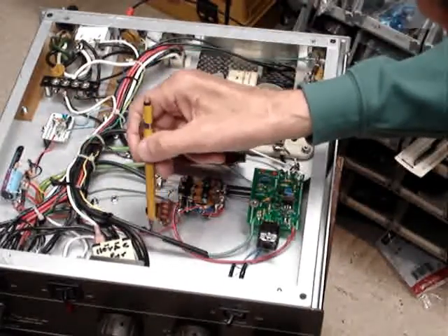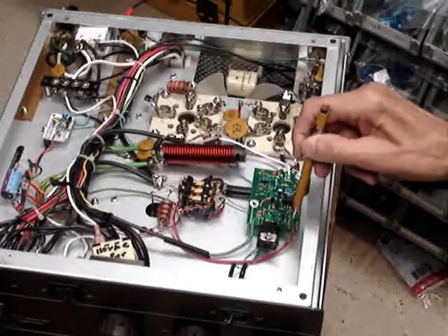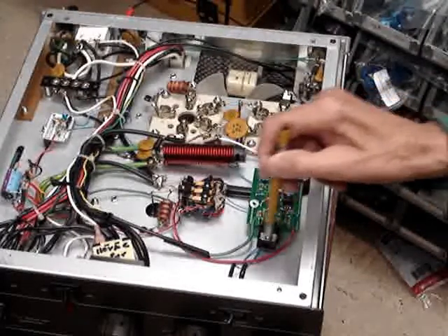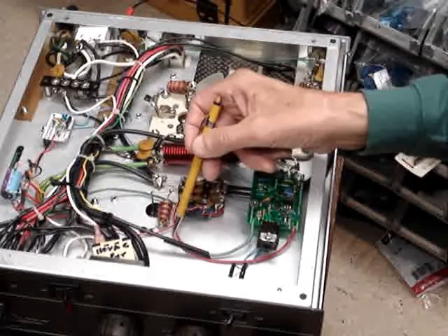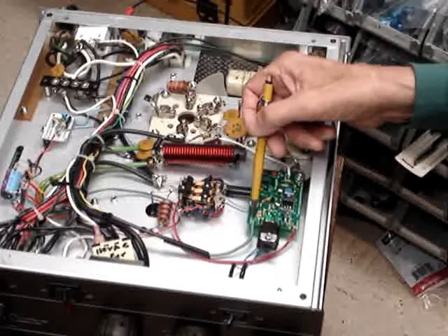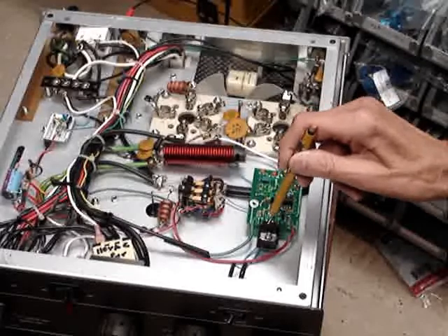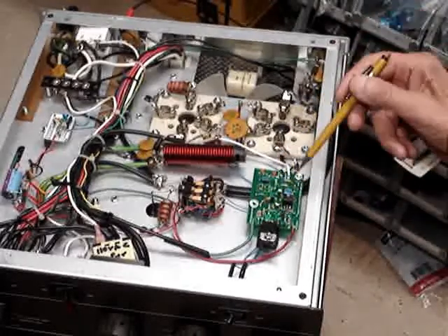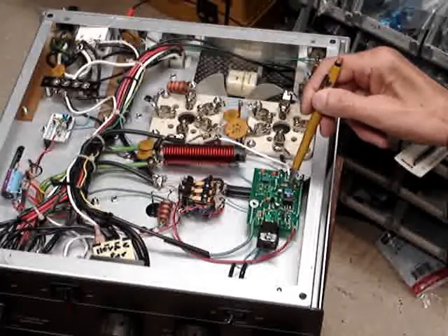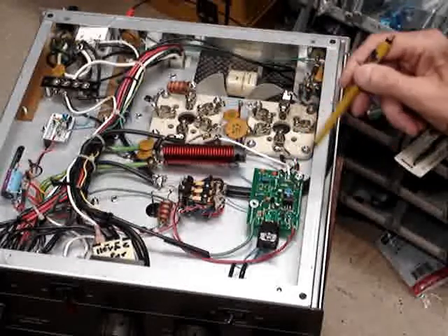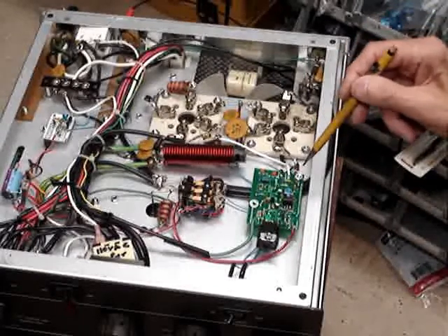And so I had to take off this wire and add a wire from the circuit here, which is the plus part on the previous diagram, over to here. So that was the wire I had to add. This wire I had to extend, the existing wire I had to extend down here to the minus part of this circuit. This transistor here controls the bias voltage. So the voltage is settable. You can't see it, but there's a little trimmer pot here. It allows you to set what voltage you want to use, anywhere between a little less than 4 volts up to about 10 volts.